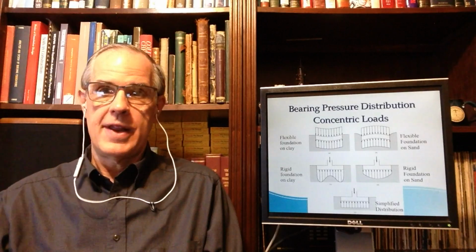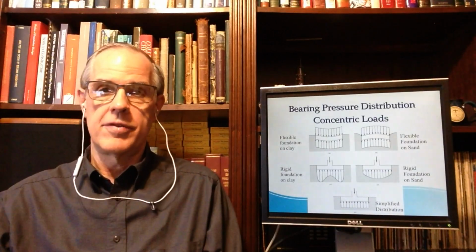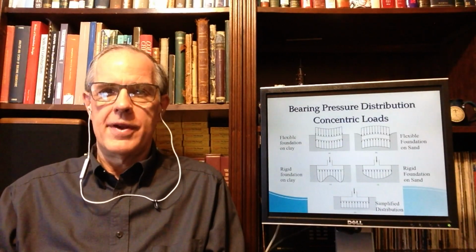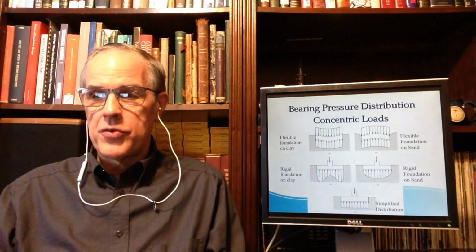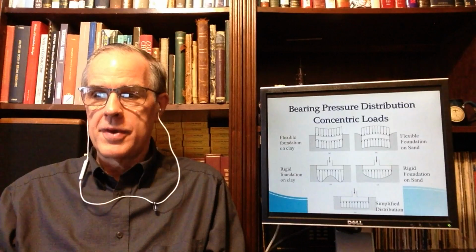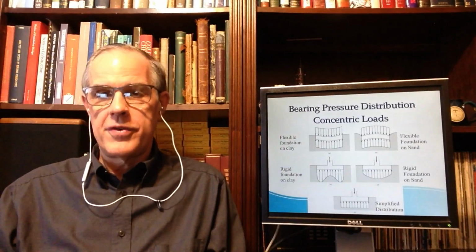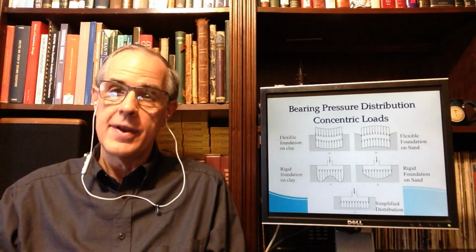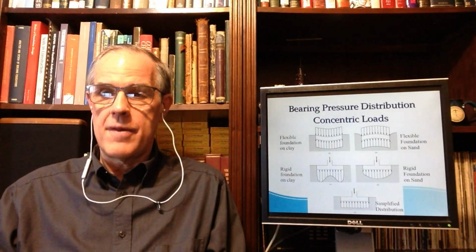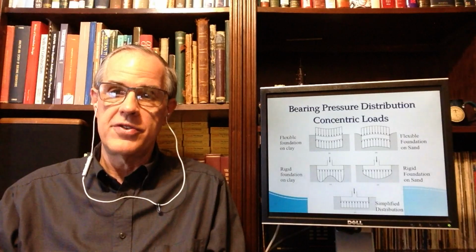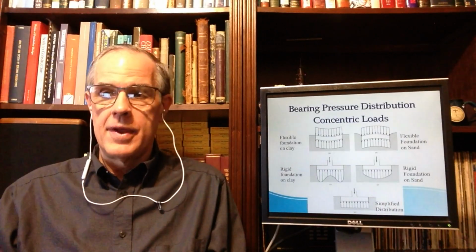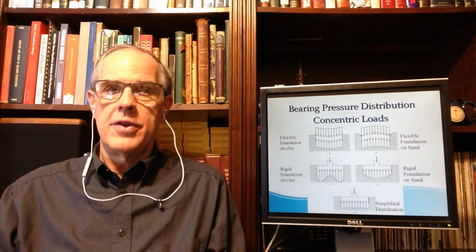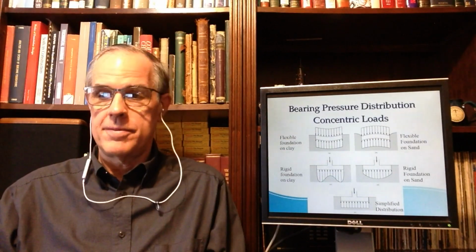With a flexible foundation, it has to be a distributed load, because flexible foundations don't do very nicely with point loads. Think about it for a while. With rigid foundations, we can talk about a concentric load, and clays tend to, with rigid foundations, and I think we saw some of this with elastic solutions, particularly go back through Verruijt. You'll see that the stresses are the highest on the edges and lowest in the center, whereas with sand it's the other way around. So sands and clays respond to loading differently, and they interact with the rigidity or lack thereof of the foundation differently.